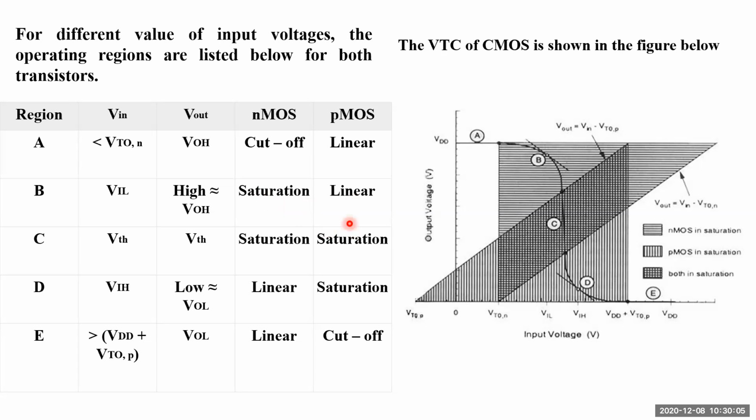But here in this region, there is some exit for the charges to go from source to drain. So that's why your PMOS is in the on state. Whenever it is in the on state, definitely VDD flows through the output, and you get a maximum output voltage. That is called VOH. So that's why your output will always be in the high state.